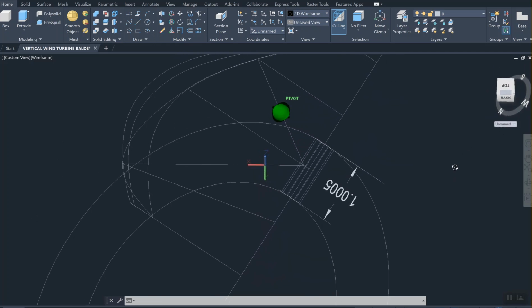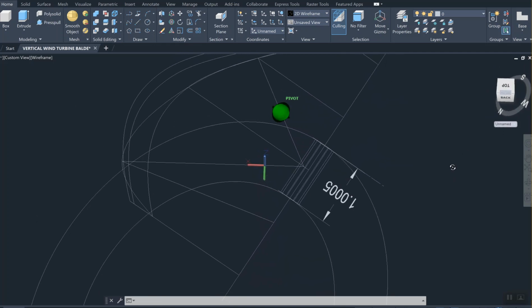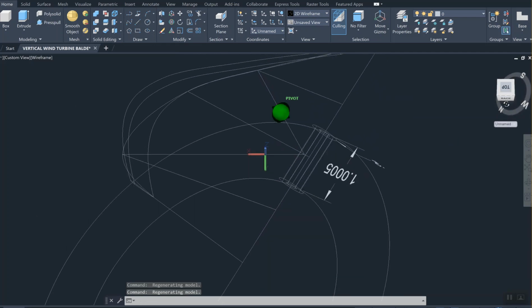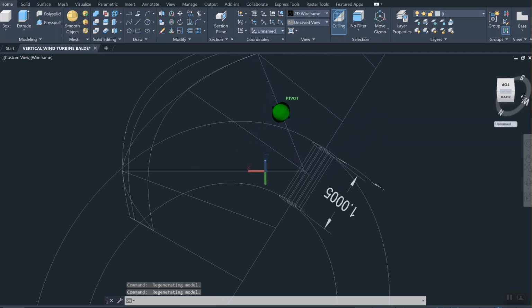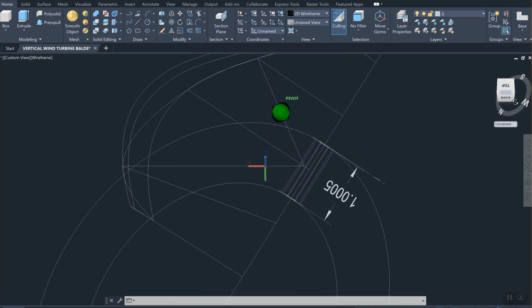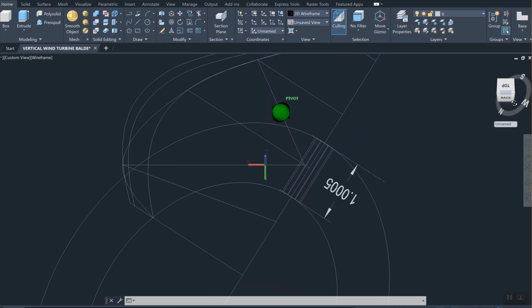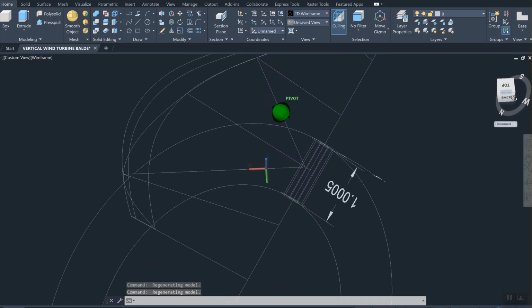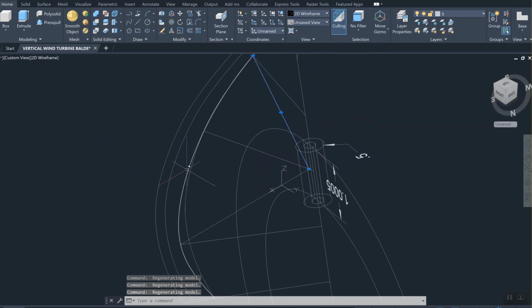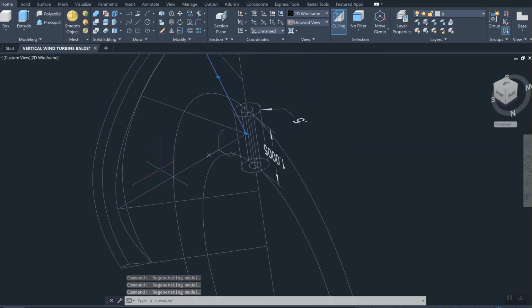To be able to draw anything perpendicular to the extrusion direction, the drawing plane should be parallel to the Z direction, by default. This is how AutoCAD operates, and basically the user coordinate system, the UCS command, will control that.